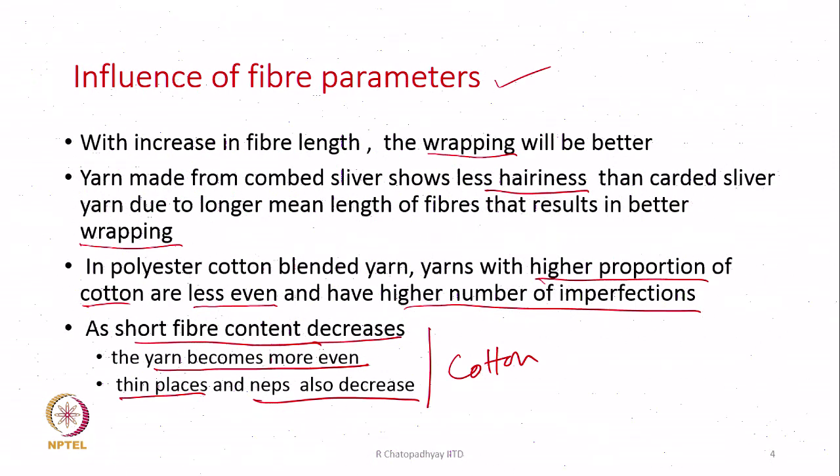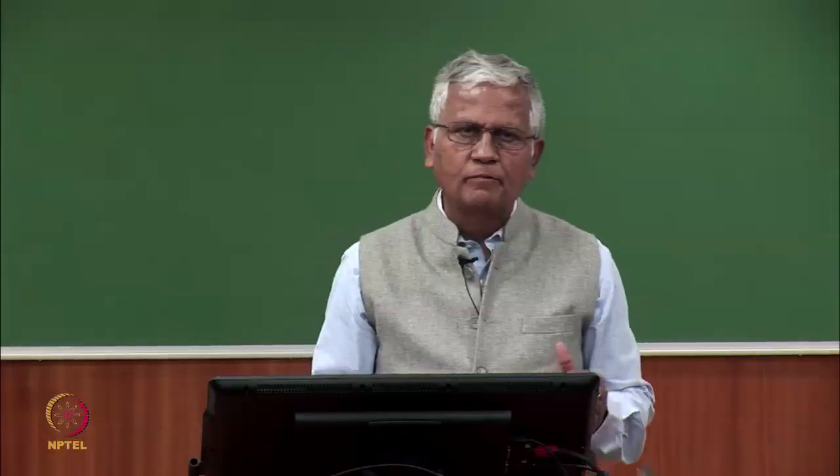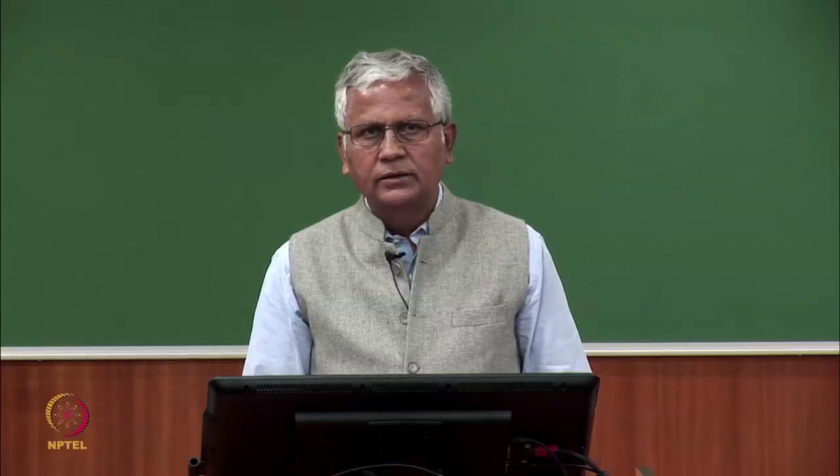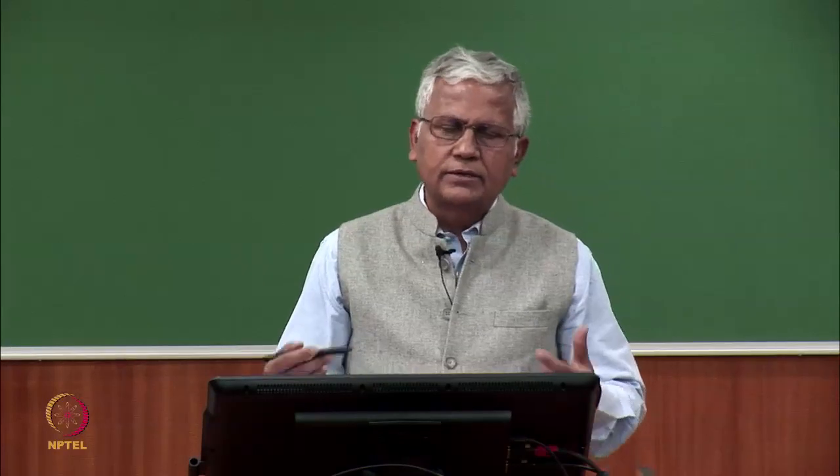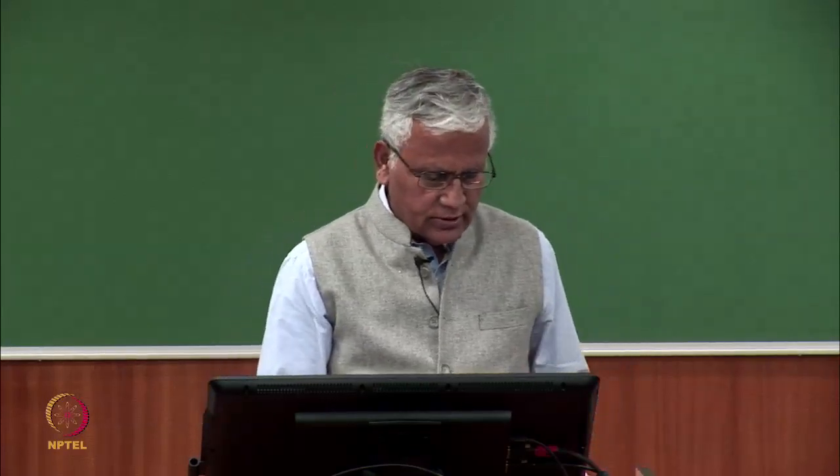We remember that cotton basically means short fibers are there, dust is there, some trash is there, and therefore, presence of cotton will always make the yarn a little more uneven, and there is a chance that thin places also can increase. So, the reverse is true if the proportion of cotton is less.